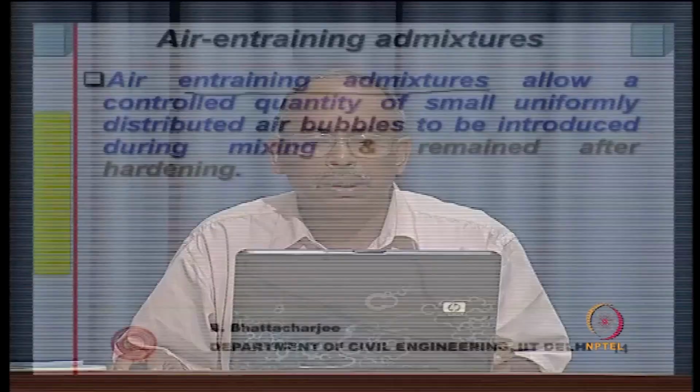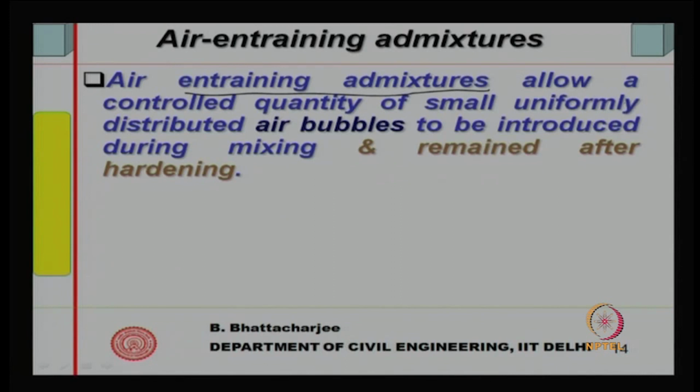So, these admixtures, if you put a controlled quantity, form small uniformly distributed air bubbles that are introduced into the concrete during mixing, and they also remain after hardening.